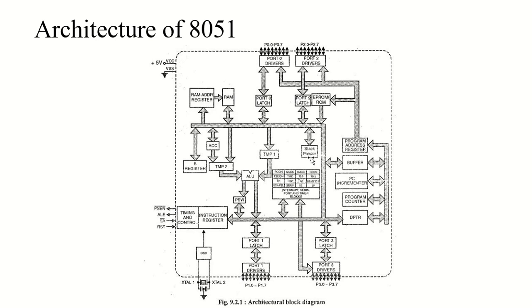Now this stack is implemented with the help of a special memory pointer register called the stack pointer, and it is of 8 bits. Of course, the stack pointer holds 8 bits, unlike the data pointer. The stack pointer contents are automatically adjusted to point to the stack, and the new memory location currently pointed to by the stack pointer is called the top of stack, right? So this is what the top of stack was.